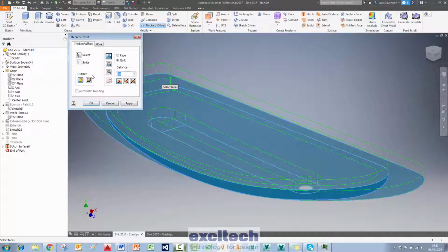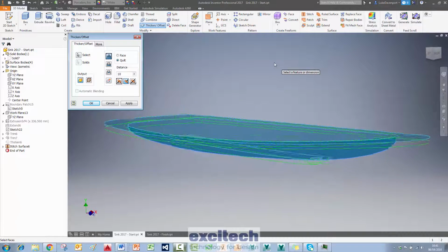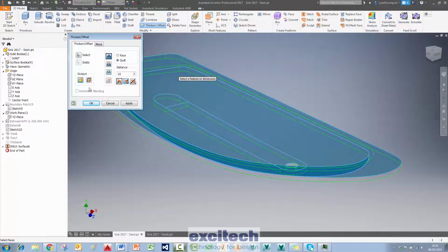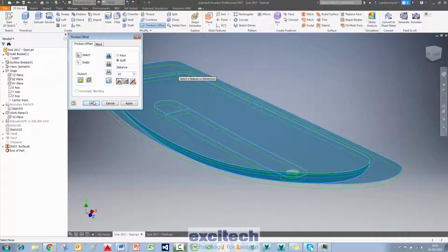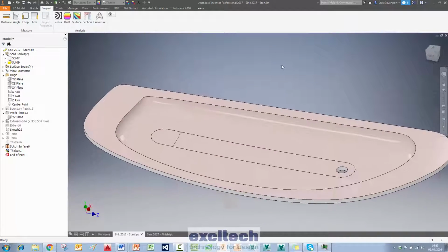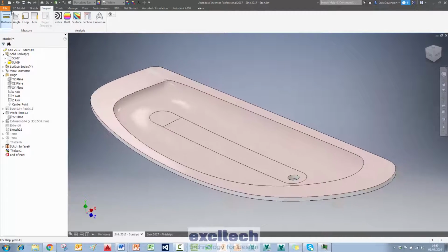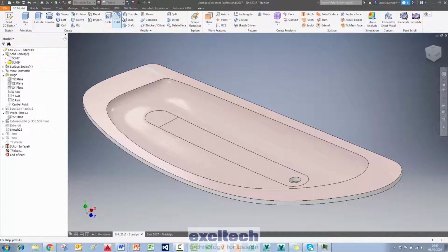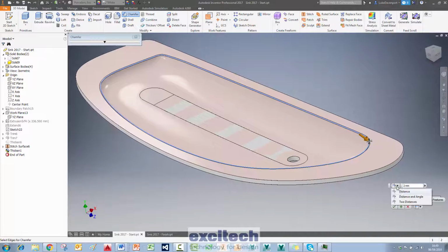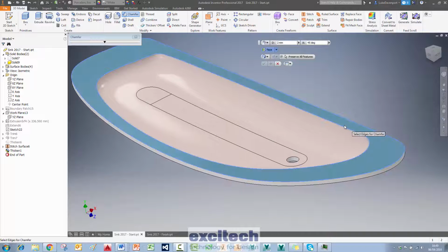And it's a bit thick. So yeah, this whole design needs to be scaled up a bit, but I'll go with this thickness here for that as a new solid. Right, that's all thickened up nicely, and so it's really just a case of getting a few chamfers and fillets on here now. So I'll get a chamfer, a distance and angle chamfer on there.